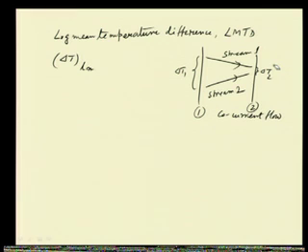Then delta T LM is the log mean temperature difference, and that is equal to (delta T 1 minus delta T 2) by ln (delta T 1 by delta T 2). So, this is the log mean temperature difference. This is also very frequently used in many situations. We will discuss details about this log mean temperature difference when we discuss the performance of heat exchangers and so on.